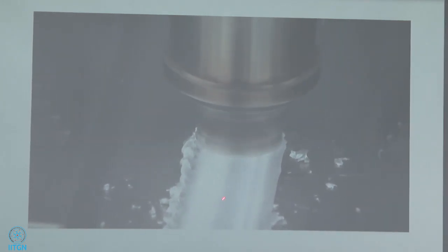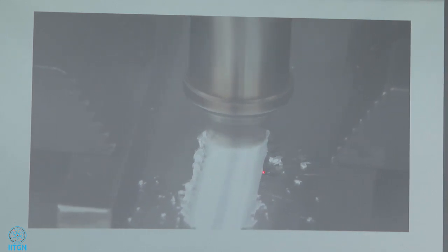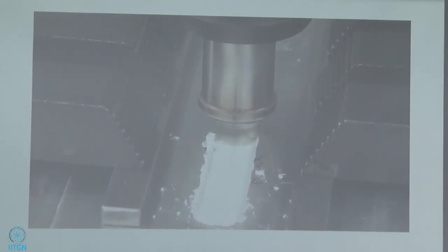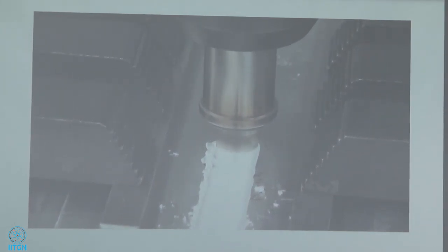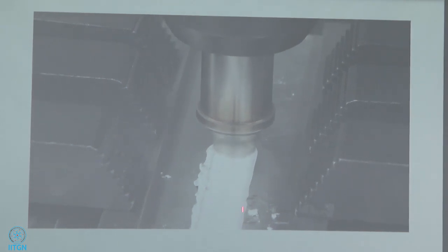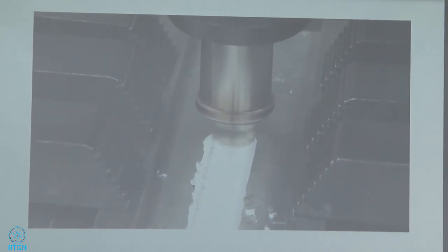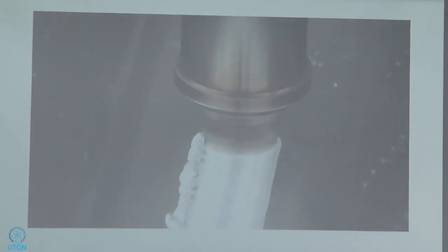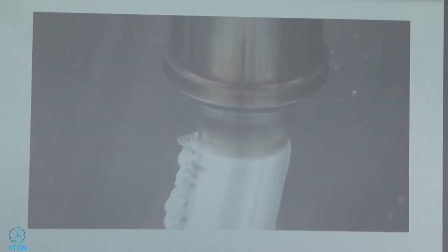As the tool moves, material from both the plates is plastically deforming and flowing in its plastic state around the rotating tool. Eventually, once the whole weld length is achieved, the tool is going to deplunge and move back in the vertical axis, and we have a fully consolidated, hopefully, joint in place.